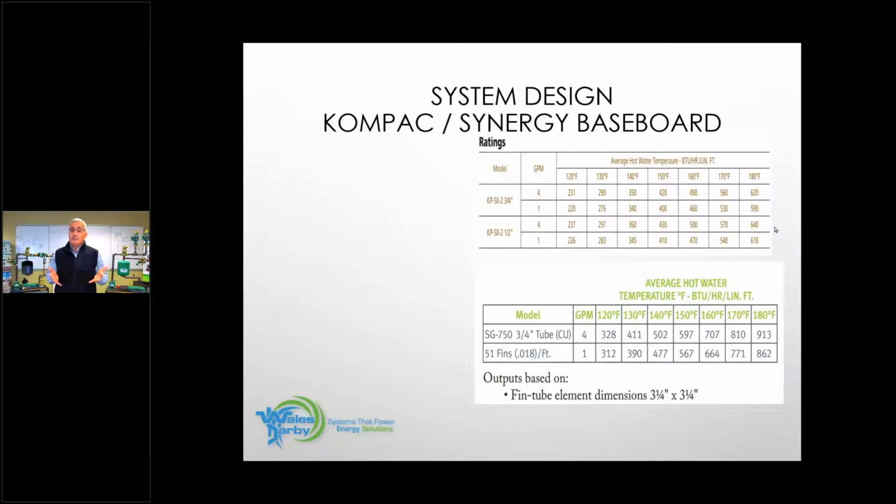And a gallon of condensate is going to be 8,080 BTUs, so I get to reabsorb that back into the boiler. Another way to think about it is if I'm attaining 95%, for every dollar I'm spending to heat my home, 95 cents goes into heating my home, 5 cents goes out the chimney. If it was a standard cast iron at 82%, 82 cents heats my home, 18 cents goes out the chimney. So I want this boiler to condense.